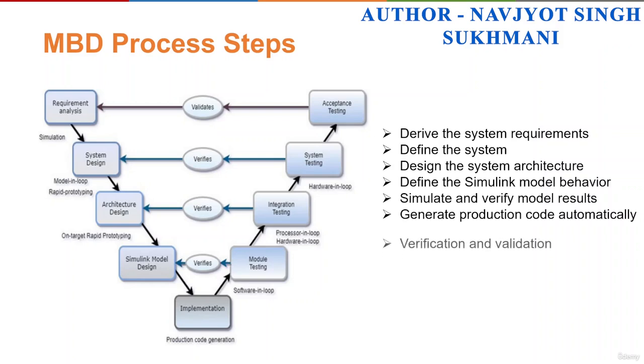So next step is verification and validation. This is all about the V&V process of MBD. Okay, so model based design with Simulink offers early and continuous verification of the component. Here you can see in this diagram it's early and continuous verification. Okay, for each design stage the test cases are prepared and auto generated, and verification is parallel with development stage.